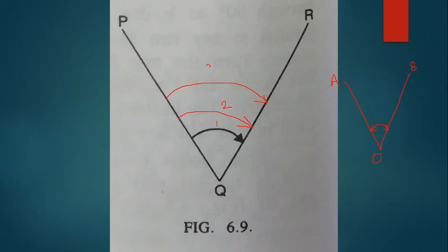So for this again I must release the upper clamp screw and rotate the telescope to bisect the ranging rod at R approximately. With this approximate bisection, fix the upper clamp screw. Then by operating the upper tangent screw only, I need to bisect the ranging rod on R exactly. Now the instrument is ready for noting down the third time reading.